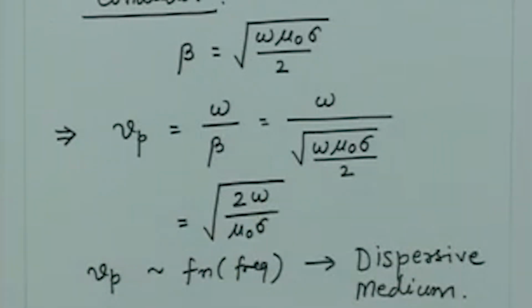So, we have some important conclusions to draw now. First of all, when the electromagnetic wave travels in the medium, we can define a parameter called the phase velocity. That is a parameter which tells you with what speed the phase, or a constant phase point on the wave, is traveling in the medium. Then we find that for a dielectric medium, the phase velocity depends upon the dielectric constant of the medium, and for dielectric constant greater than 1, the phase velocity is always less than the phase velocity in vacuum. That means the wave always slows down when it travels in a medium with higher dielectric constant.